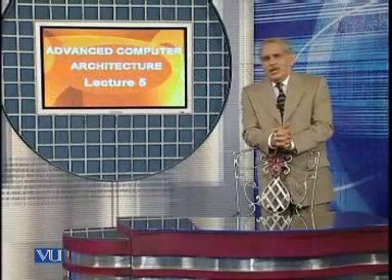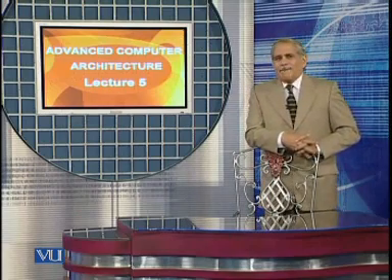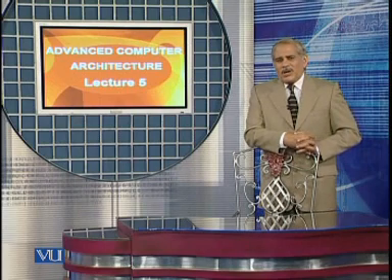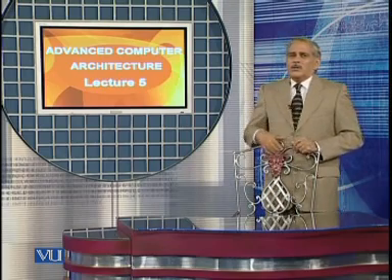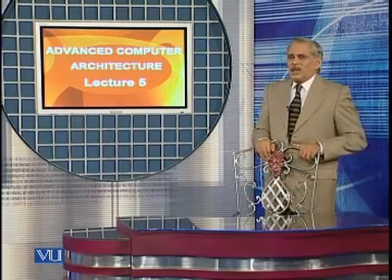However, the 16-bit field used over here is used as immediate data in some cases. The immediate data is obtained by using this 16-bit value and passing it through a sign extender, and this sign extender extends the sign bit to convert this value into 32-bit data.